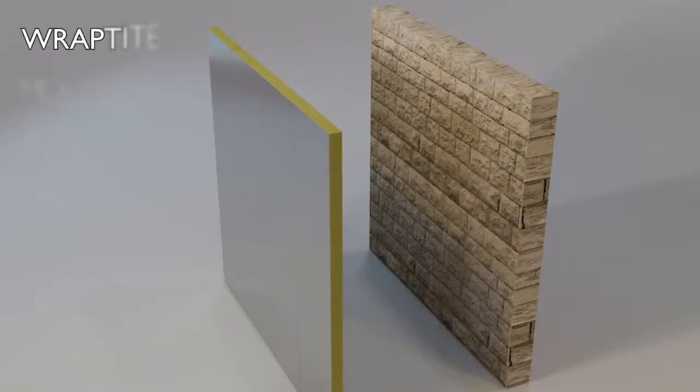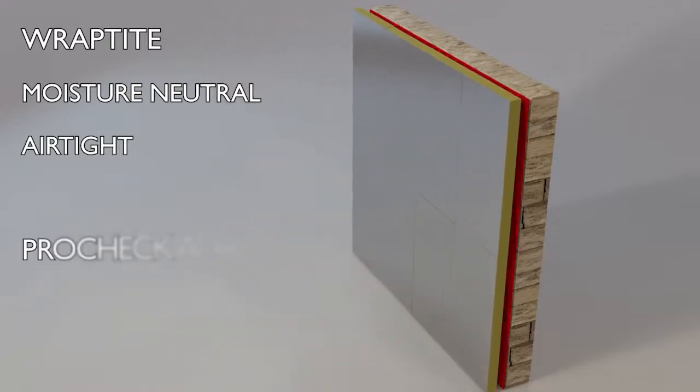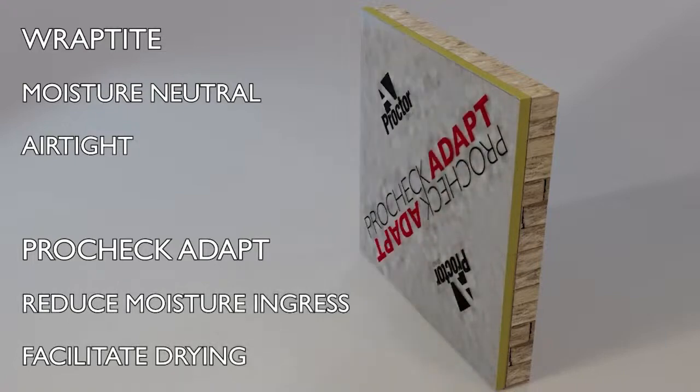In this type of wall, Airtight can again be used as a moisture-neutral air barrier over the masonry, which will block air leakage without inhibiting the flow of moisture. Project Adapt can also be used over the inside face of the insulation to manage the ingress of moisture in colder conditions whilst reducing the impact on drying out.